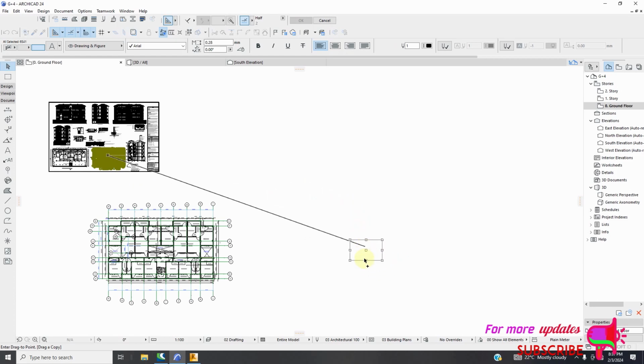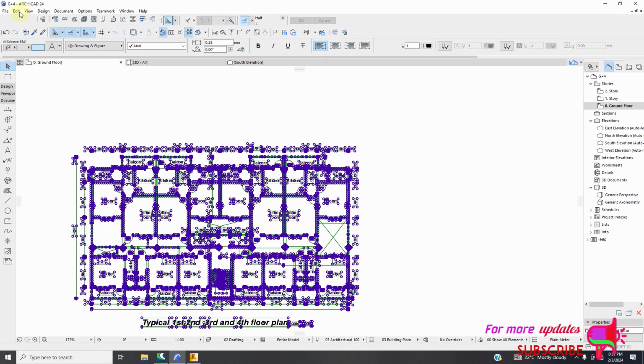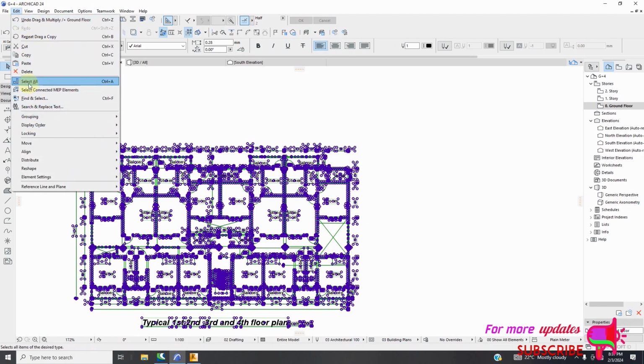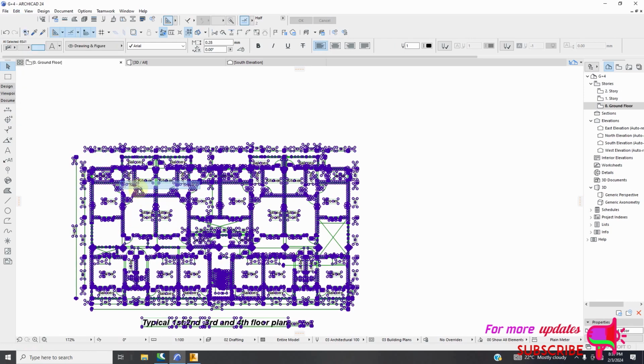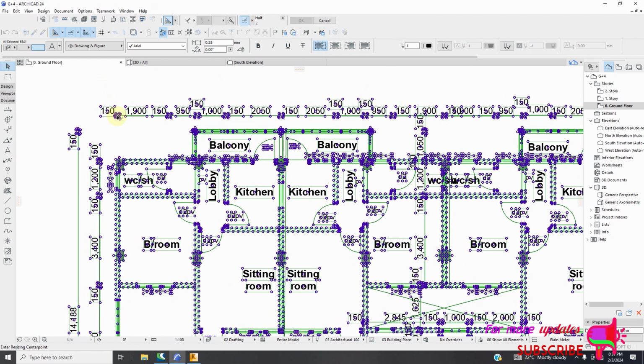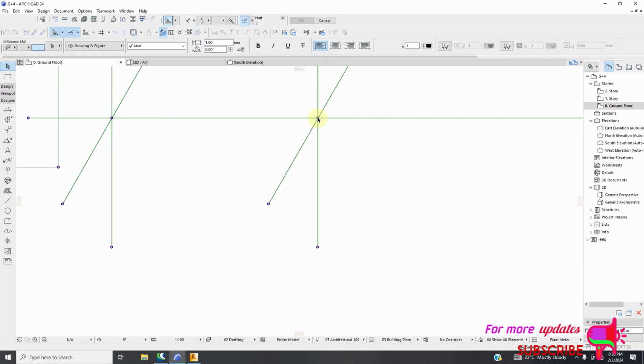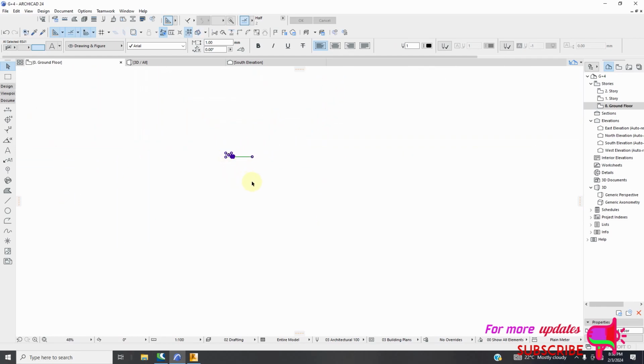You can see this drawing is not scaled. So the next thing I did was to scale. I went here, then reshape, resize, because this is how you're going to receive your drawing. You're the one to add your grids. So I selected it from here to there, held Shift D, and this was 150. You can see now this drawing is scaled.